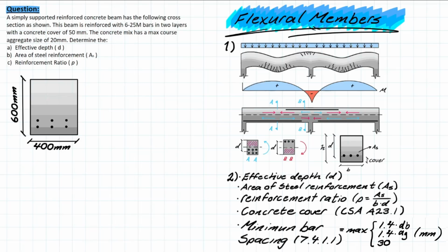An area of steel reinforcement is represented by As. And the reason that we have this effective depth is because we're going to be taking this as a design variable for future problems where we have tensile force being directed from the reinforcement and then a compressive force acting in the face of this compression block.